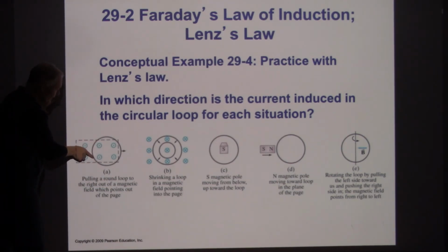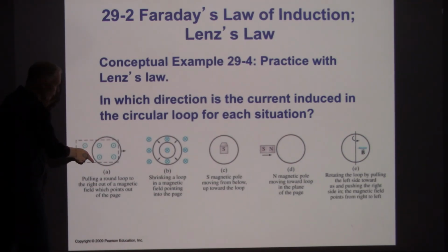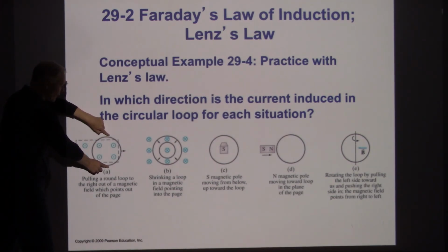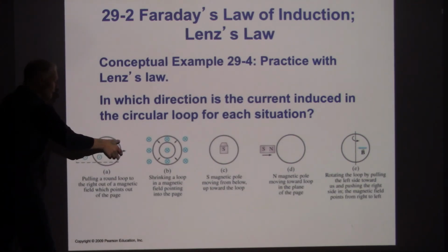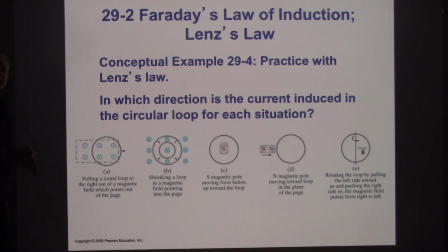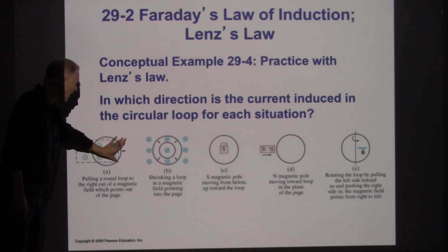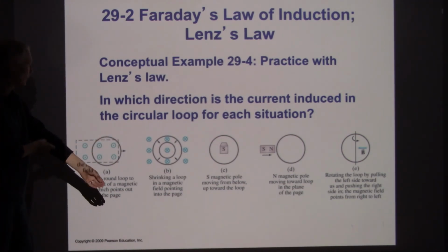It's over in this region where that force is lined up with the wiring itself, and the charges will get pushed. So they're being pushed from here. Most forcefully right from here, not quite as much here, here, and here, and then it drops down to zero. And the reason we're getting a net EMF is because this portion has exited the magnetic field, and so there's not going to be any forces on those charges anymore. So this one is not being offset by an opposing force, and these forces are able to generate the current.